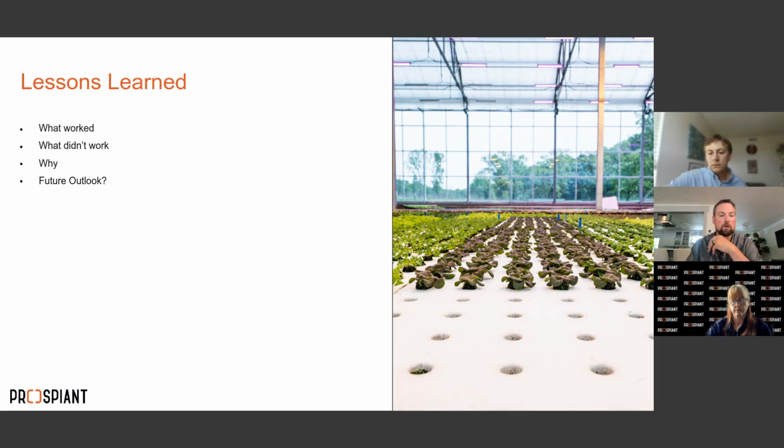You got to think about growing in a greenhouse. If you're trying to do a passive greenhouse in some environments, let's just say down south, your root zone is going to be too hot for an NFT in most cases. It's going to be the same temperature as the outdoor air temperature, and plants don't like to have their roots that warm. So you see deep water culture being more popular in hotter climates, especially if you're doing a passively ventilated greenhouse. More often than not, though, because people want full control of the production, they want to do a mechanically ventilated greenhouse and have that under complete automated controls.